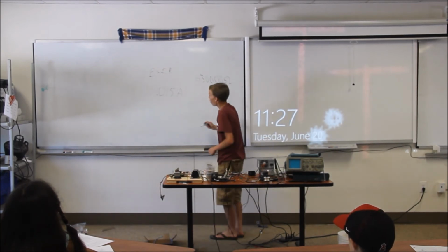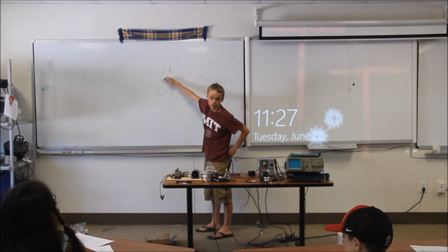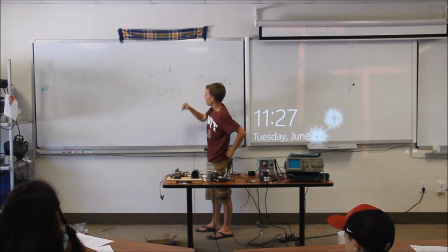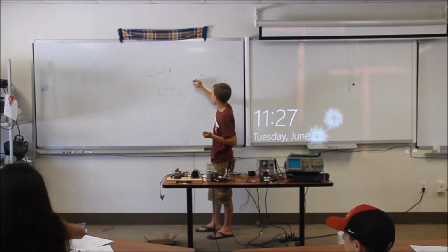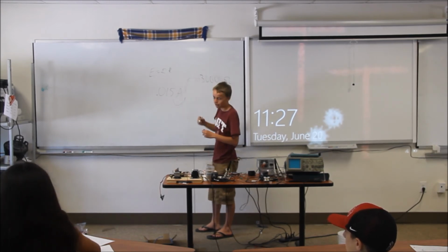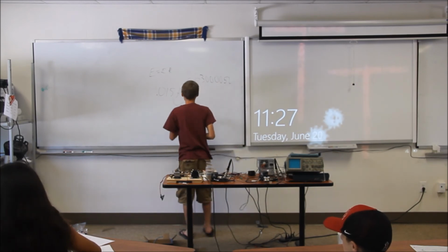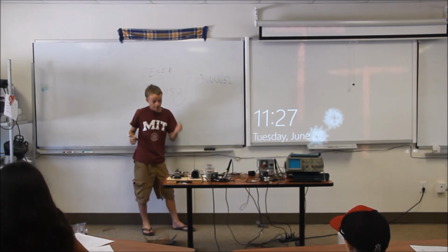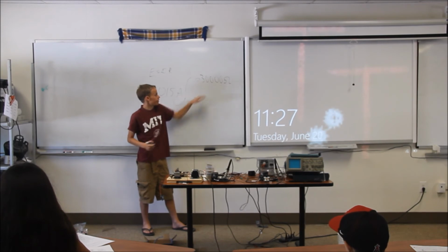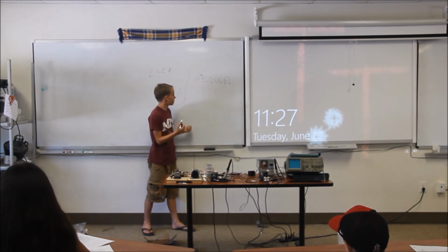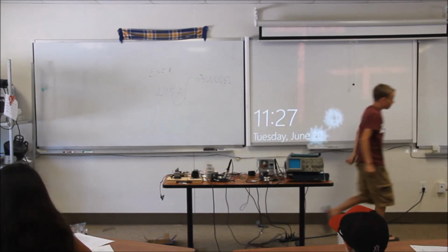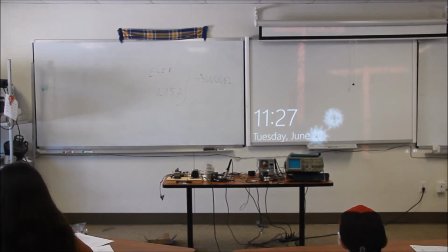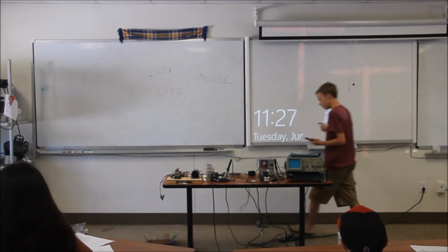And so, our E, or voltage, is unknown. And so we'll multiply the current that can kill somebody by this resistance right here. Now remember that when my hands were dry, they had this resistance. When my hands were wet, they had a resistance way lower than that. I kind of forgot what it was. But that resistance can be calculated to figure out the recommended voltage that is lethal.